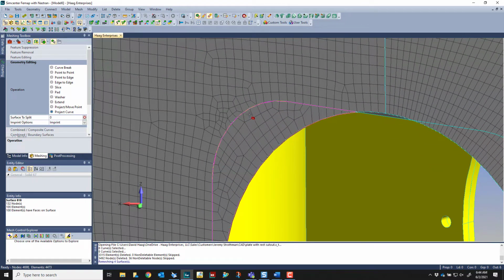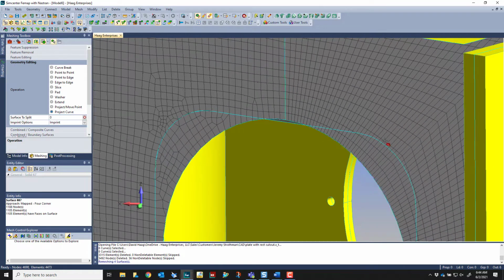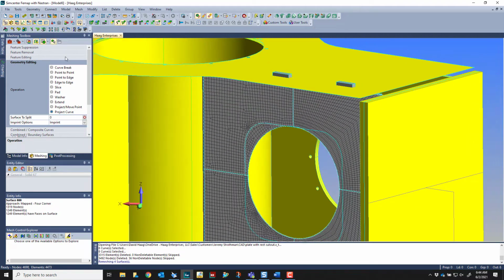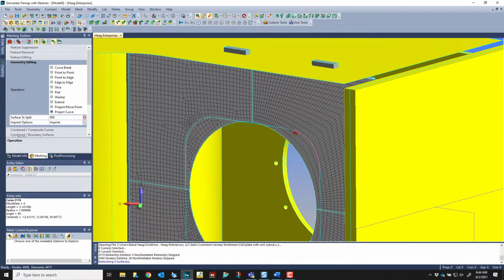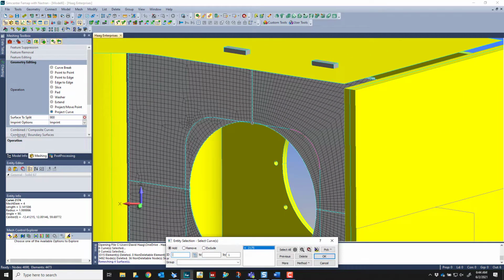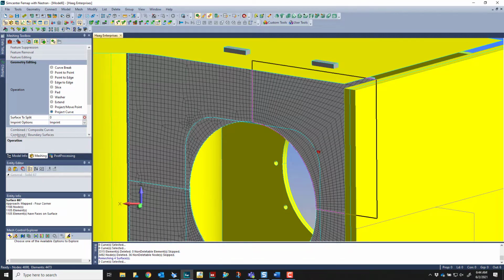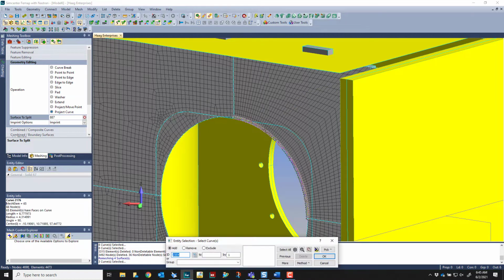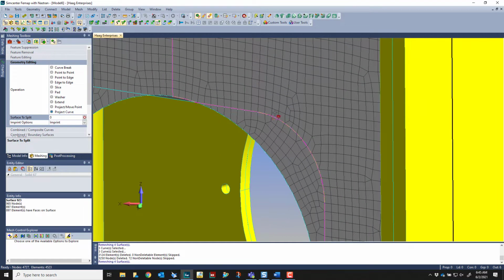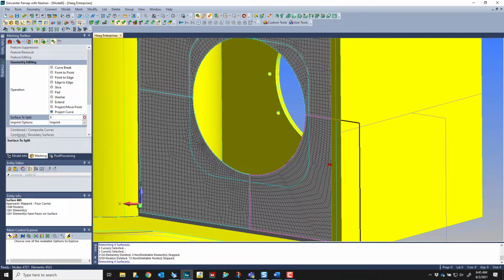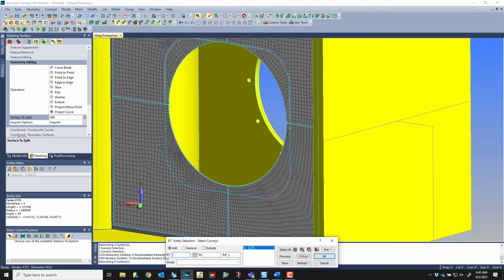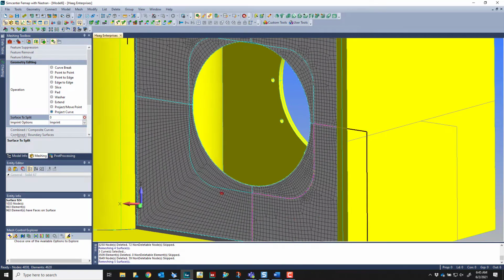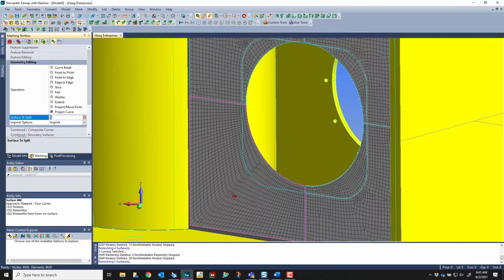So it split the surface, did an auto remesh on the fly, but over here it did not, and that's because these are individual surfaces. So that's okay. We'll just go back and pick the surface and do the same thing on this side. So surface to select is this one. Pick our edges. I missed that initial surface upon the first selection, and you'll see that our mesh updates there. Reselect this surface, and then we'll do it again for the fourth.